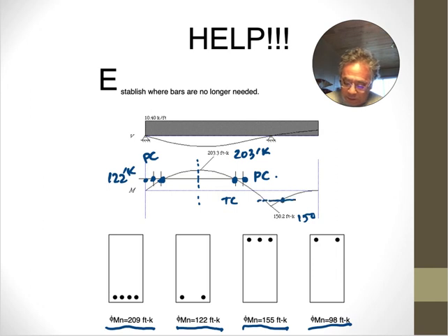That would be 98. And then you would have to add outside of that D or 12 bar diameter. So again, this is theoretically where you would cut it, and this is where you're proposing to cut it. And next, you have to check LD. So development length L.